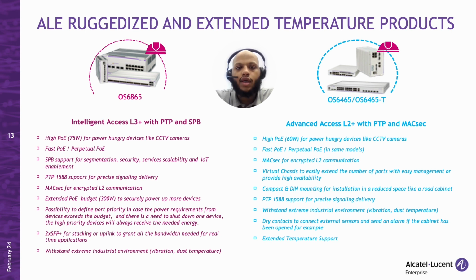And then there's the extended temperature model. The difference is that this one is designed to operate in an extended temperature range, offering reliable operation from minus 10 degrees Celsius all the way to 60 degrees Celsius ambient temperature range. The fans don't run unless the switch is operated with an ambient temperature of 45 degrees Celsius to 60. The fan will remain off from minus 10 all the way to 45 degrees Celsius.